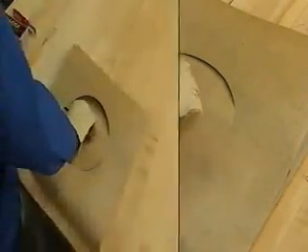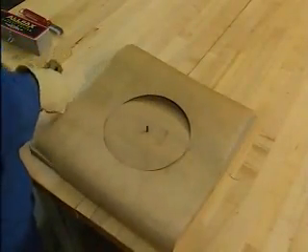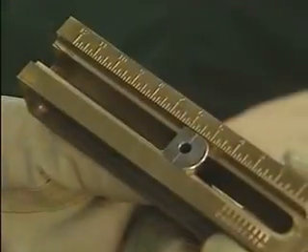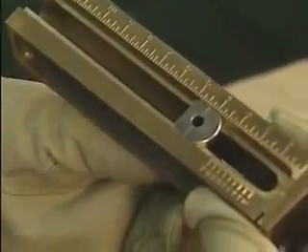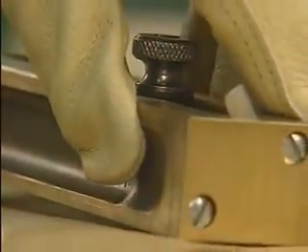The mechanic then removes the cutting tool from the pin and readjusts the blade to the inside diameter measurement of the pipe flange. He places the cutting tool back on the pin and turns it one complete circle to cut the inside edge of the gasket.